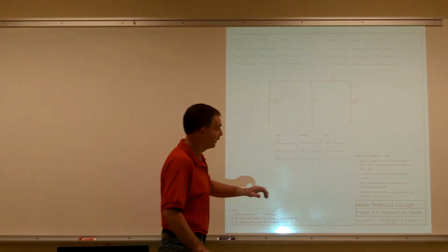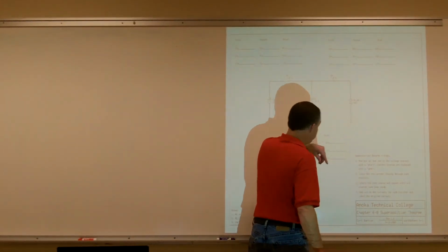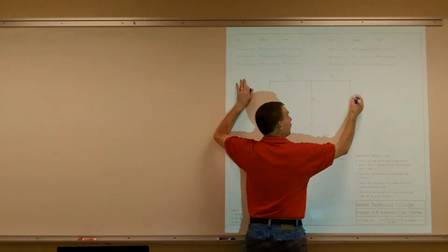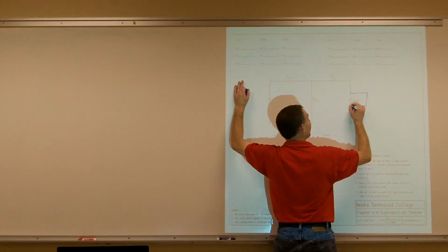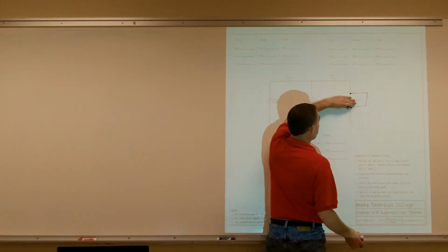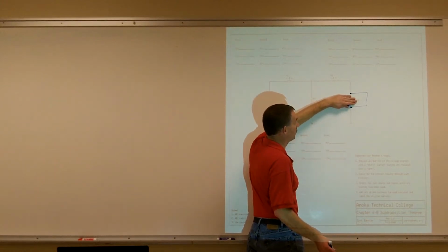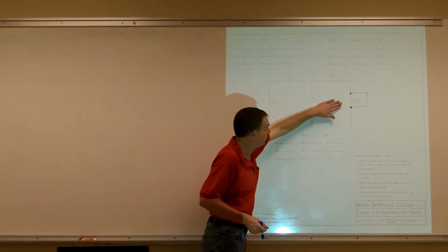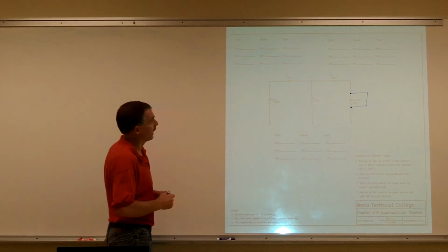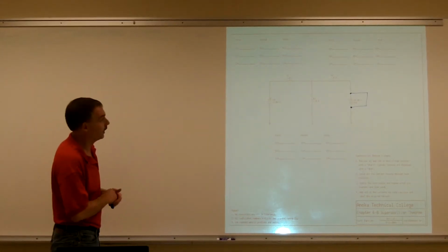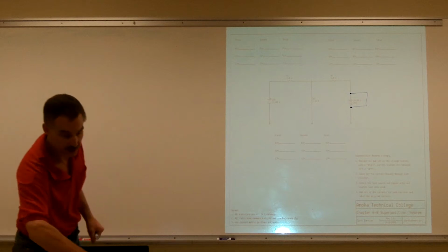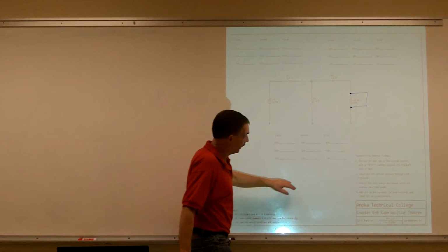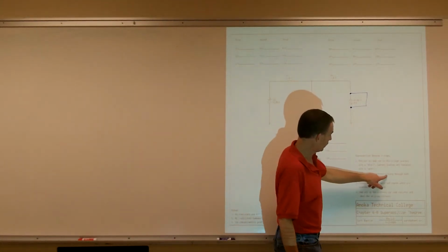All right, so it says replace all but one of the voltage sources with a short. It doesn't matter, we can do number 1 or number 2. So let's do number 2. We're going to remove our power supply. So in your lab, you're going to remove the power supply and then put a short where you removed the power supply. Now it gets to be a little bit tricky in the DAC, but you'll have to try figuring that out. Some of these superposition ones, you might want to use the regular DC power supplies so you understand the concept of it. Then you replace one, and then it says solve for the currents flowing through each resistor.